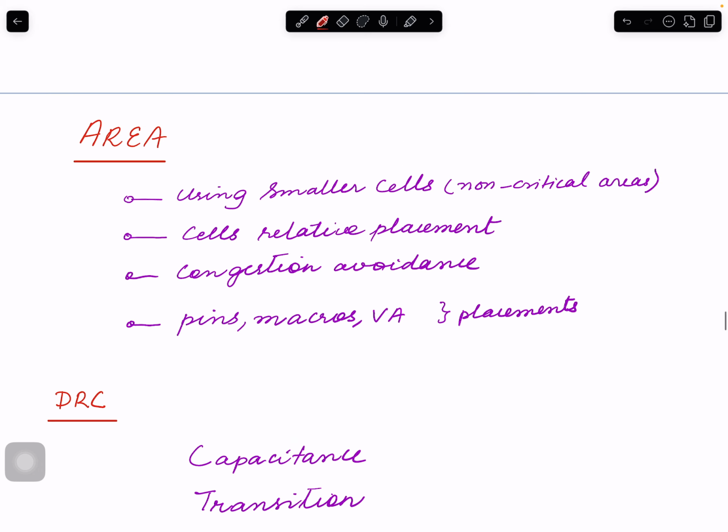Okay, if you remember from CMOS fundamentals, the size of the cell is what? Its width and its length. The current is proportional to W over L. So the length is fixed, right? For a particular technology, the length of the channel, the length of the transistor, is the minimum and is fixed. You don't want to increase that.